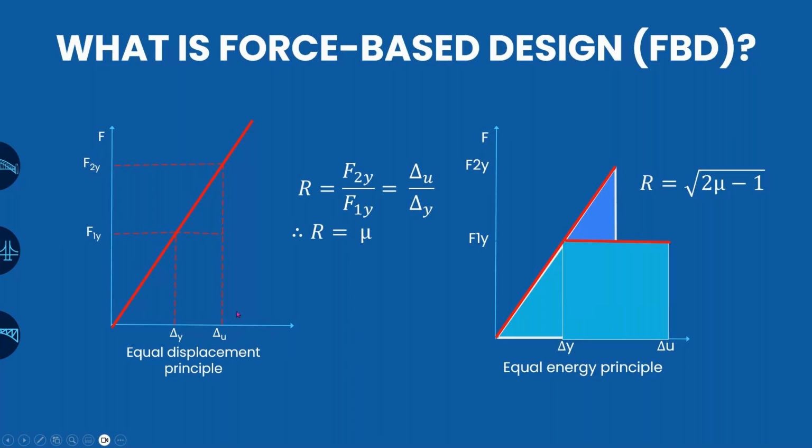So, if you have a long period structure, that is, a structure having a fundamental period of greater than 1 second, it is called a long period structure. For the long period structure, even when a structure experiences non-linear behavior under seismic loading, its maximum displacement will remain relatively similar to the displacement it would experience under purely elastic conditions. So regardless of strength, the structure will remain entirely elastic in the seismic event.